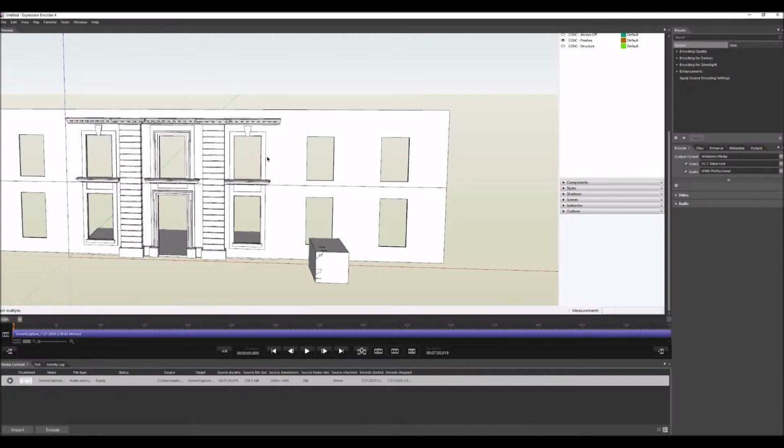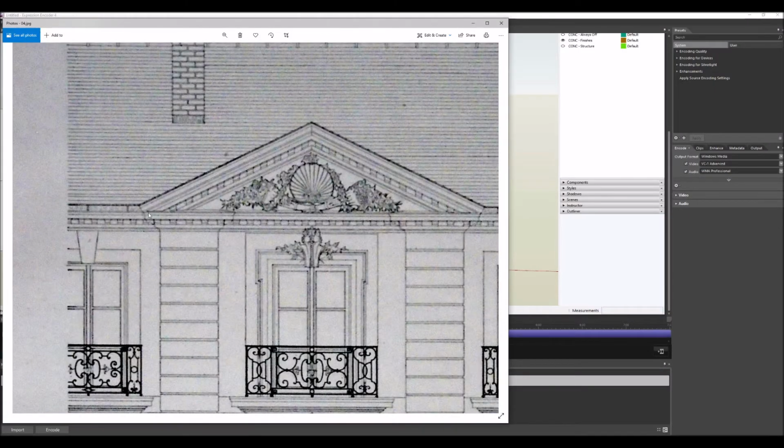And traditionally, the corona is continuous all the way across, and the corona angles up. The cyma angles up, but the cyma actually stops here. It does not continue along the side here. What you're seeing in the drawing is not the cyma, that is a piece of profile, metal profile for the gutter. So the corona is continuous, and then the cyma follows the shape of the pediment. And the traditional profile for the cyma is laid out along this edge, which I'll show you in the model.